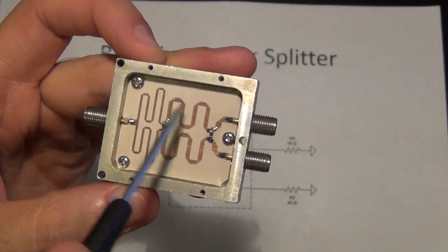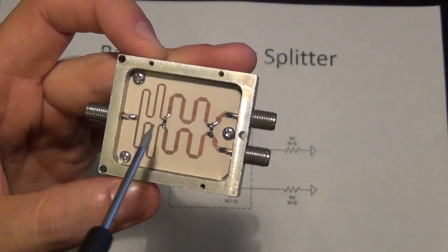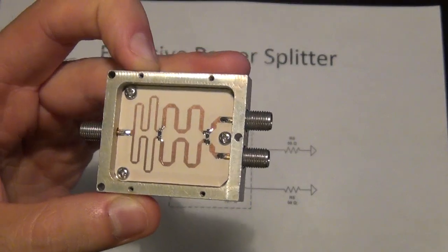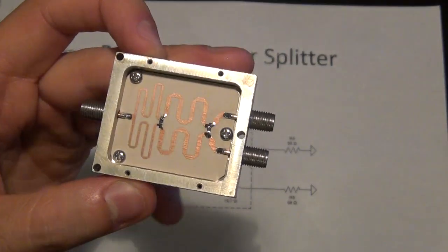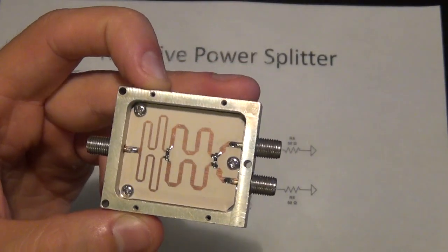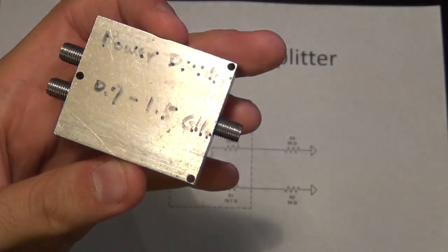You can see the thickness of the lines change and so on, but you can see at DC, at very, very low frequencies, these 3 are actually all connected together. But remember, that's not a 50 ohm environment anymore because these are all shorted together. So this thing does not do a very good job at low frequencies. And that's why this has a rated frequency range, and it only works within that frequency range.